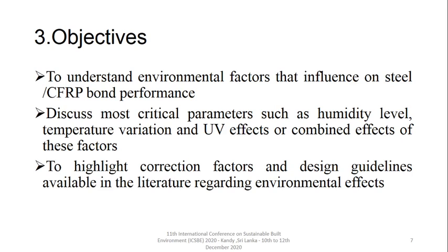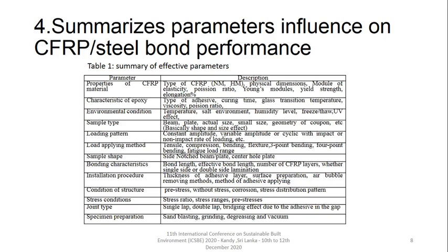Objectives. To understand environmental factors that influence steel-CFRP bond performance, discuss the most critical parameters such as humidity level, temperature variation and UV effects or combined effects of these factors, and to highlight correction factors and design guidelines available in the literature regarding environmental effects.